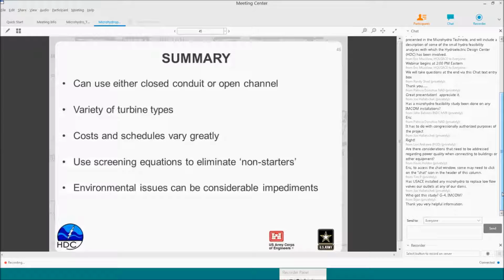Generally speaking, when we're talking about hydro on the scale here, once you get into, shall we say, a 10 kilowatt or larger, we have really 2 choices. We can either do a synchronous generator or an induction generator. Induction will have some issues with the quality, if you will, but they're not that big. Synchronous will be more expensive, slightly cleaner, but for the purposes of these installations, unless you're running isolated, generally speaking, an induction generator will work.